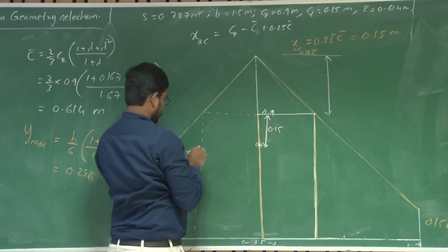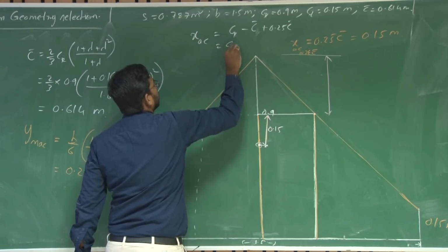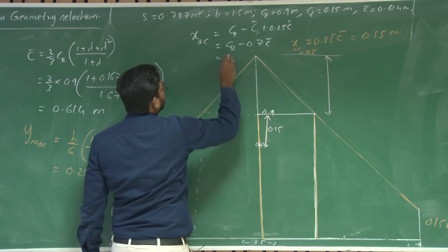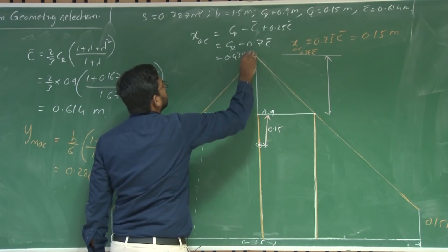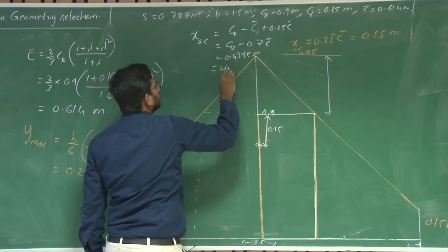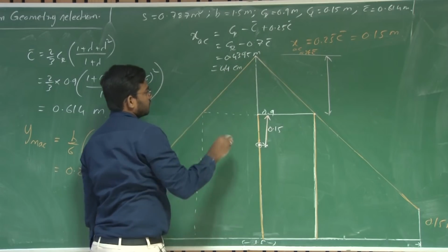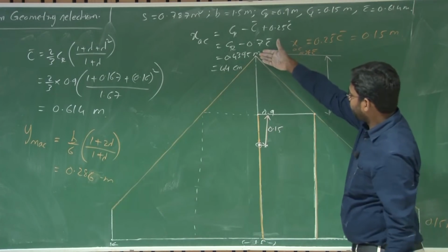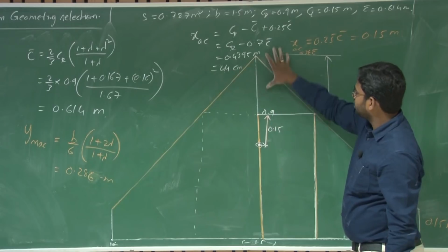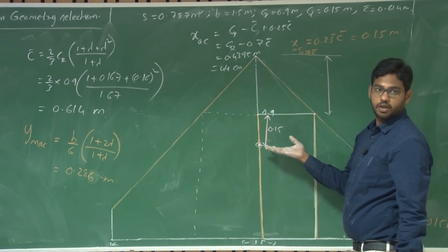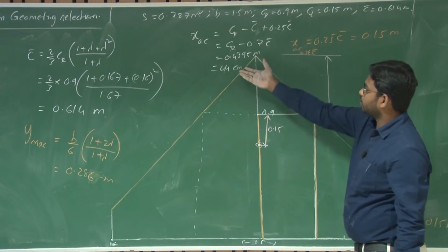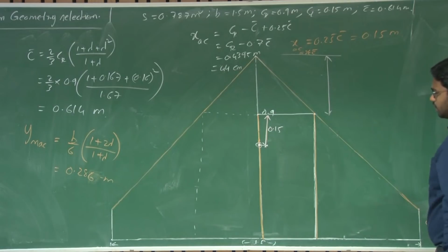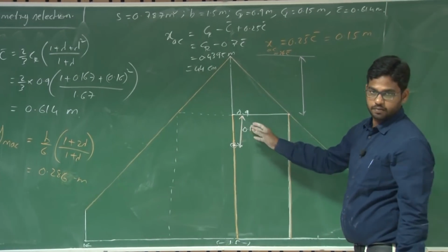So this is going to be CR minus 0.75 C bar, which is approximately 0.4395 meters, or 44 centimeters. So you can simply take a tape and measure the aerodynamic center of this configuration, which should be approximately 44 centimeters from the leading edge of the root chord. You can look at it physically.